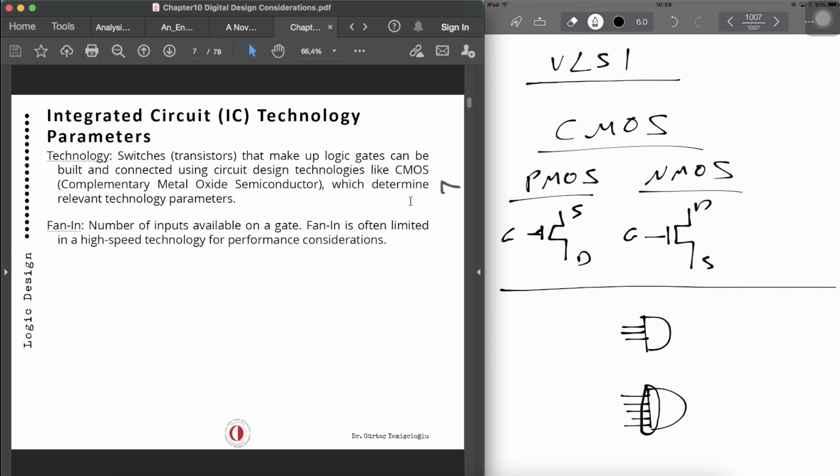So rather than having a 5 input gate, what we can do is have a 3 input one, and then also implement a 2 input one. Then we can have 4 inputs, or maybe one more input. So you can use 2, 3 input gates and do it like that. That's also acceptable. So we can use this one as well.